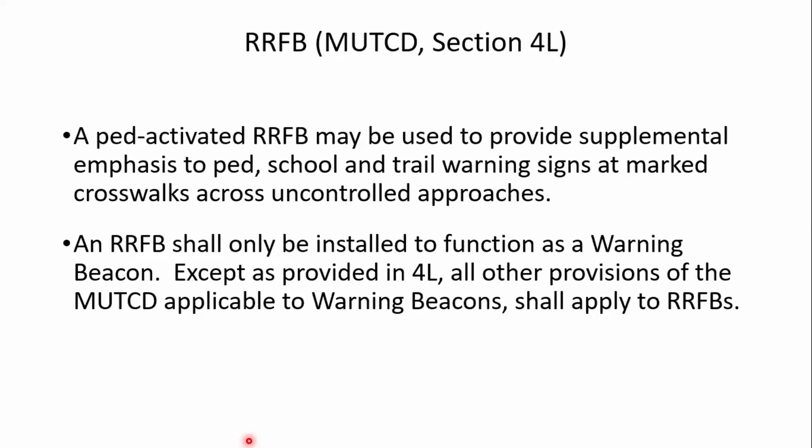Section 4L of the MUTCD addresses RRFBs. And notice they say a PED-activated RRFB may be used to provide supplemental emphasis to pedestrian, school, and trail warning signs at marked crosswalks across uncontrolled approaches. An RRFB shall only be installed to function as a warning beacon. Except as provided in Section 4L, all other provisions of the MUTCD applicable to warning beacons shall apply to RRFBs.